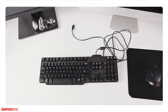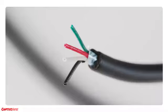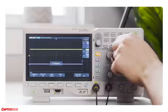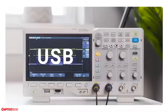I want to talk about this Modbus protocol that Juan mentioned. You know, what is a protocol? What does that mean? And for this demonstration, I have this old dusty keyboard from like 2003. The standard keyboard uses around 104 keys. So if we take apart this wire, you might expect to see 104 tiny individual wires. But that's not the case at all. There's only 4 wires, and in fact, only 2 of them carry data. That's because this keyboard is communicating through a protocol called Universal Serial Bus, or USB.